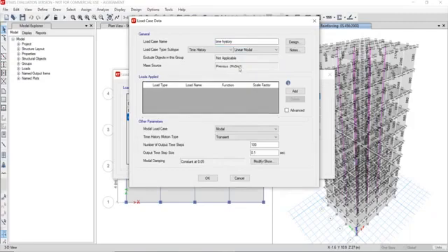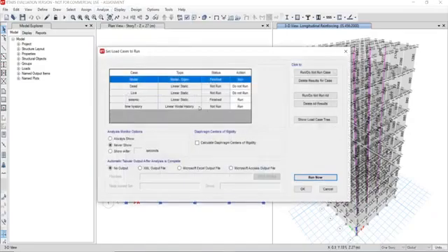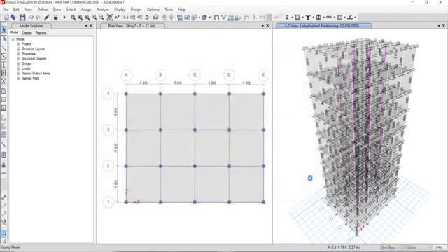Go for time history analysis. Add our load applied in acceleration load type, load name U1, function is our given time history function, and scale factor is 1633.5. We already saw we only have the x direction, so no need to add another load case. Then click OK. Click OK. Now analyze, set load cases to analyze, as in the previous case. Now click run now.